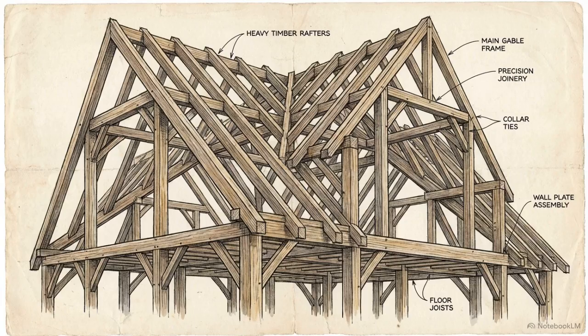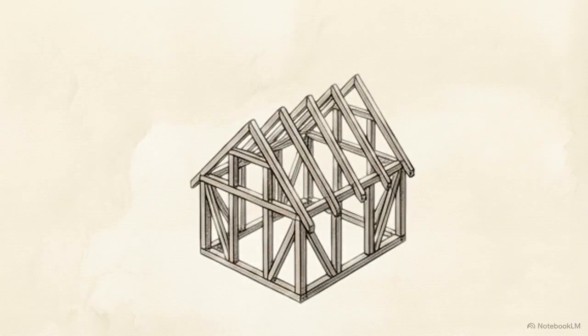With the internal skeleton stabilized against gravity and tension, the frame needs secondary supports to hold the actual exterior shell. We add purlins. These are horizontal supports placed squarely across the middle section of the sloping rafters. Rafters covering long distances can sag under heavy loads. Purlins intersect them halfway down, adding extra midspan support, specifically designed to bear the weight.